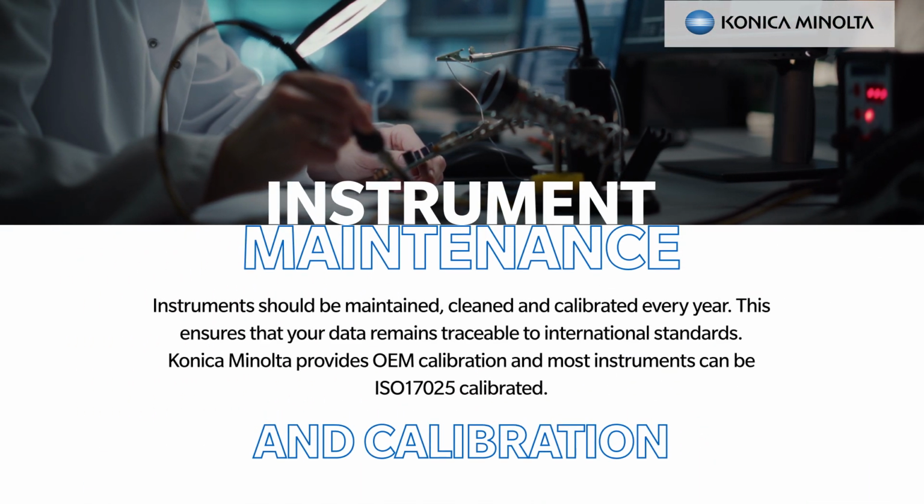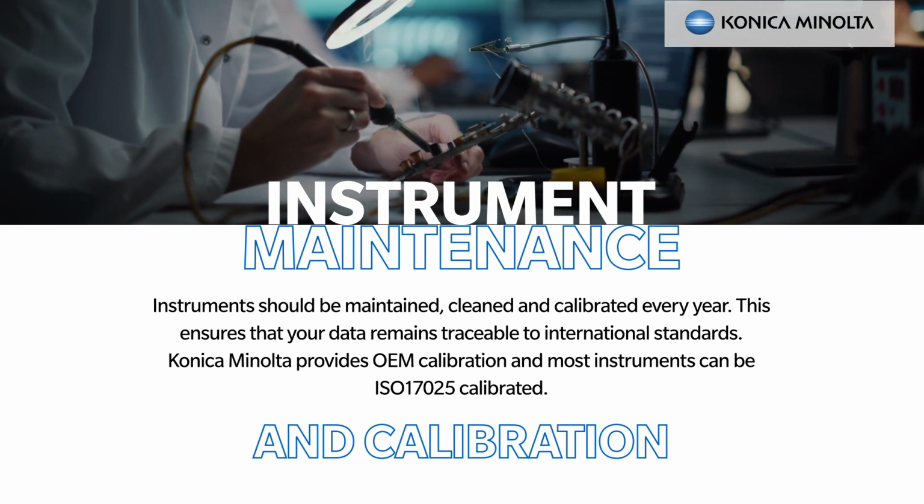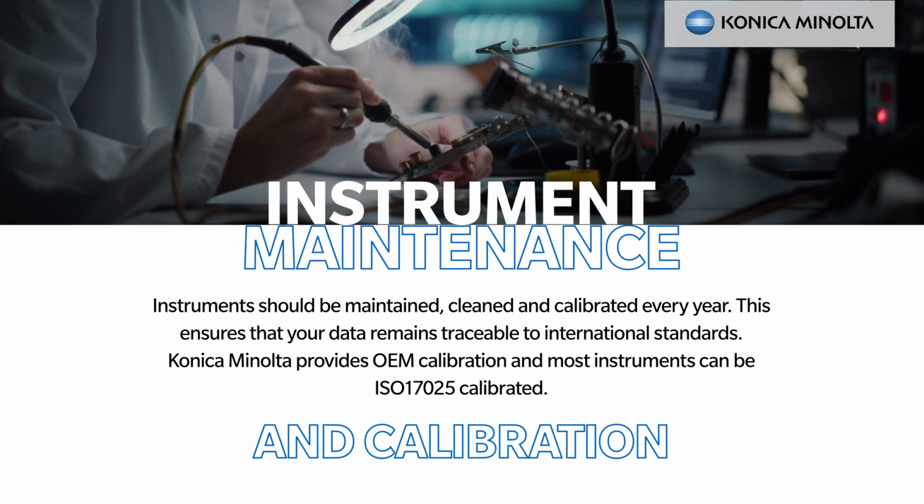Instruments should be maintained as per manufacturer's specification. Typically, this means that every year they're maintained, adjusted and calibrated against data that is traceable to international standards. This not only ensures that the instrument is in the best working condition, it also provides a certificate for your records and traceability for your measurement data.